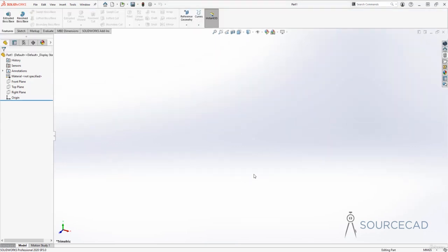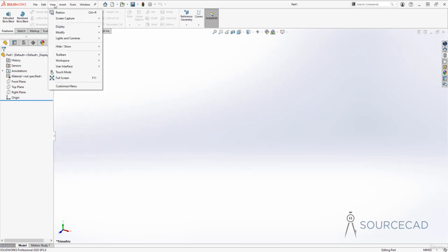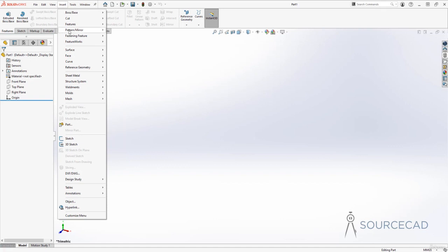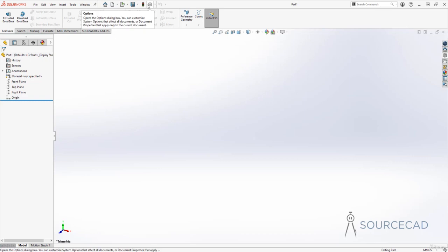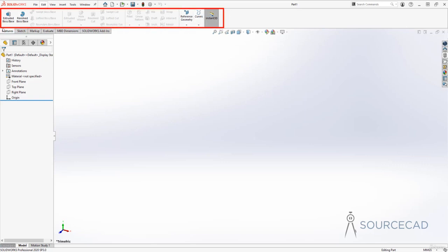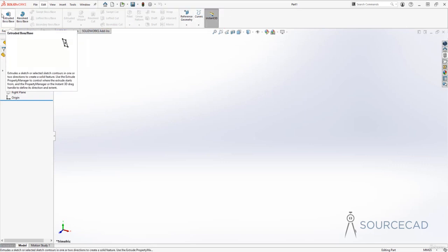And this is the main work area. In this work area, we have already explored this file menu, which has all the file related options. So insert has insert options, tools has tool options, and so on. Then we have the quick access toolbar. Now the quick access toolbar is available here because I've made it like that. But by default, you may find the quick access toolbar in the command manager somewhere here. This area is called command manager, and you may find the quick access toolbar here.